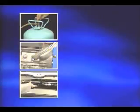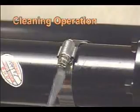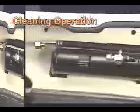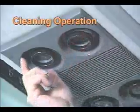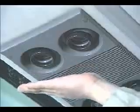Then replace refrigerant, lubricant oil, and dryer, and perform cleaning operation. The cleaning operation is for removing any impurities remaining in the refrigerant line. As for the procedure, repeat dryer replacement 2 or 3 times after air conditioner operation. If the air conditioner gets cool enough, we may judge that impurities have been removed.